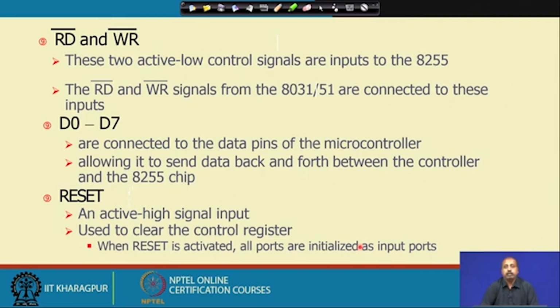So, if you want to operate the 8255 in input mode only, you do not have to do any control word setting. You can start directly, but if you want some of the port bits to be output, then we have to put some control word in those things. So, this way we can use the 8255 for various operations, and we will see some examples by which we can do this interfacing.